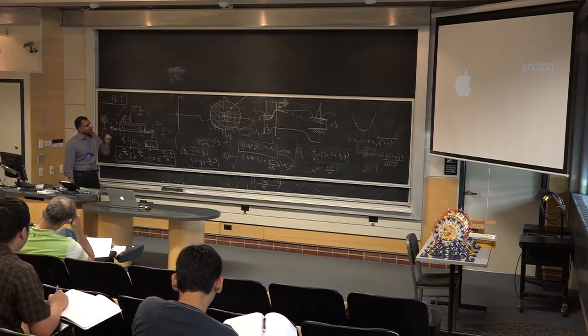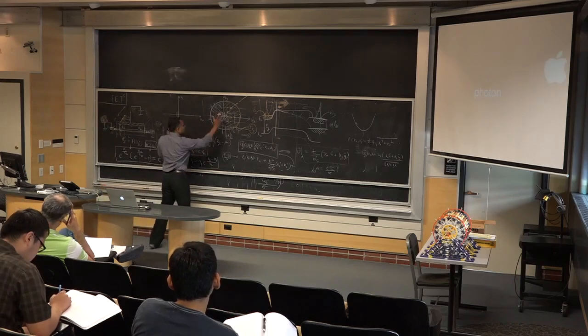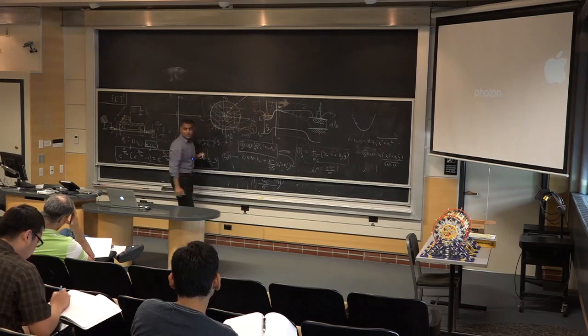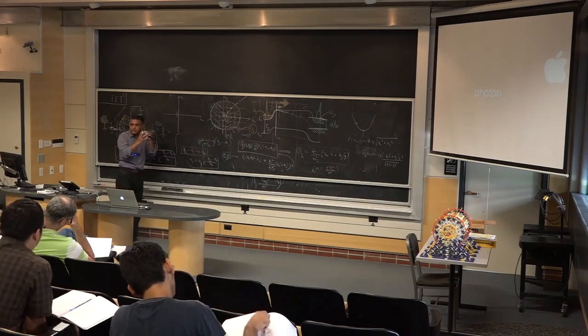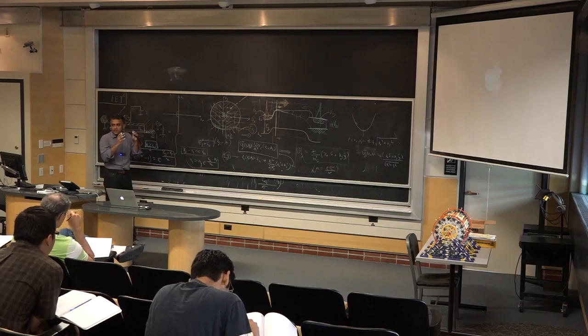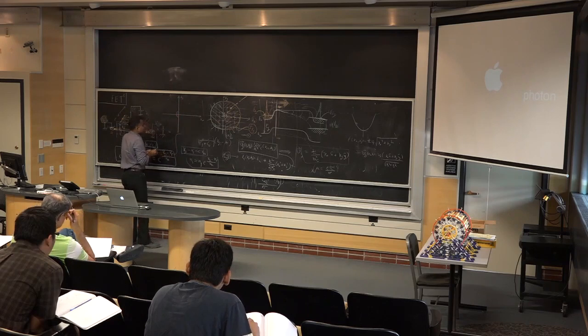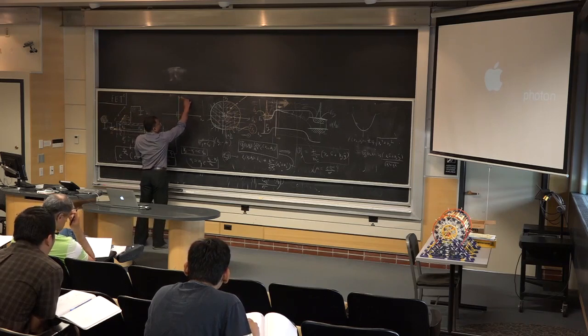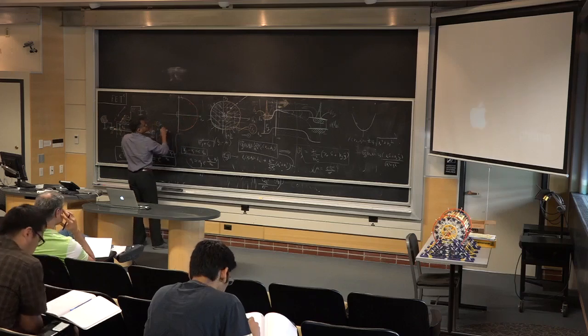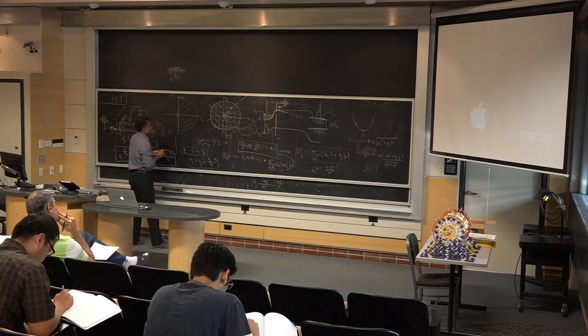So, with that thought in mind, if this area has shrunk, clearly you can see the right side has to increase to keep the area the same at the same gate voltage. Does that make sense? I mean, the area must be the same. Or in other words, the carrier density is the same, and therefore, let me just sketch it, maybe a little bigger circle on the right, something like that. So more carriers are going to the right.